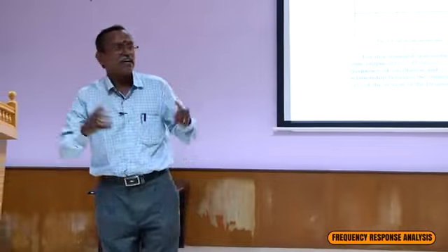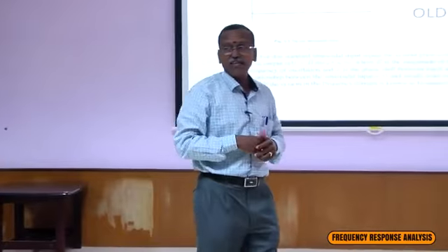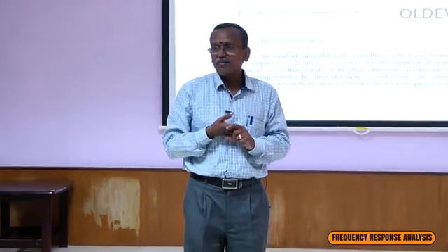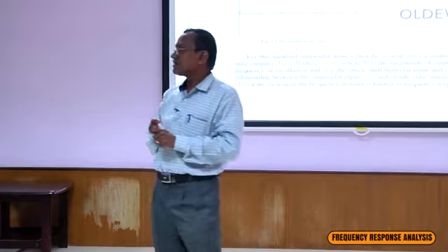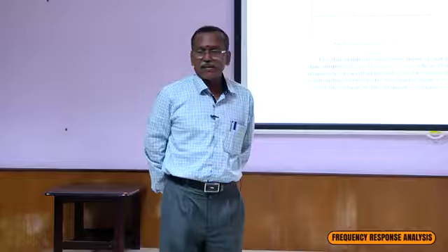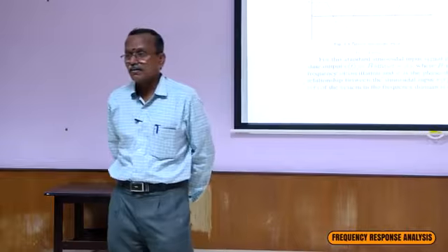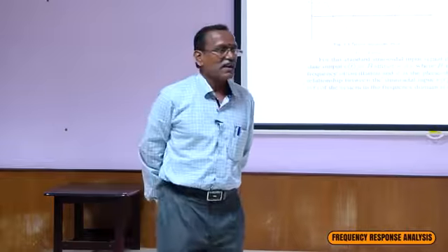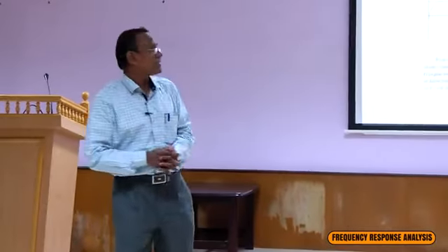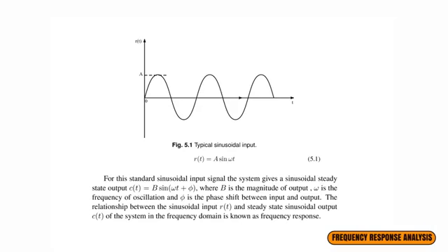That's why if you want to see the steady state response, we have to look in the frequency domain, where steady state responses can be easily seen. Because of that, they are handling things in the frequency domain. Two reasons: one is that differential equations are converted into algebraic equations, and steady state responses can be conveniently seen in the frequency domain. Because of these two reasons, we are handling the problems in the frequency domain.